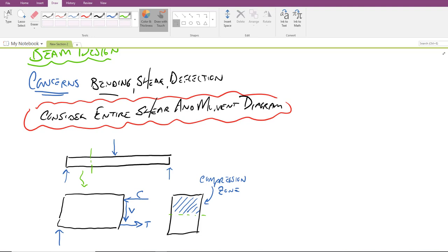However, in the bottom, concrete is not good in tension, and so we actually run rebar down the bottom of the beam, essentially where we have negative bending, and I'm going to draw two pieces of rebar running through the length of the beam in our cross section, and we note that this is where the tension force is being carried.